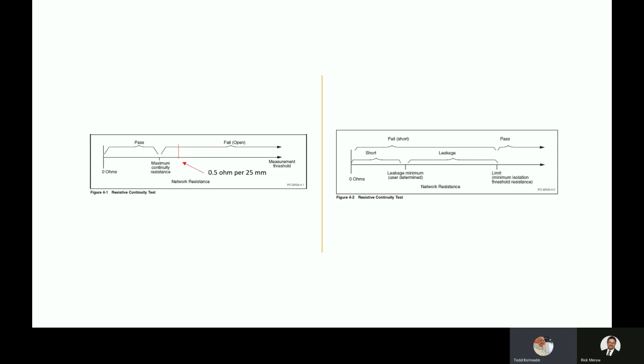Well, this referee allows us to go back to our vendor or the supplier, or you might have to go all the way back to the engineering group and say, hey, this net is exhibiting 17 ohms. We can't get it to pass at 10. But based on the referee number for copper, we can see that the number that we're getting for this length of trace is actually within specification and can still be allowed to pass. So that's breaking down table 4.1.